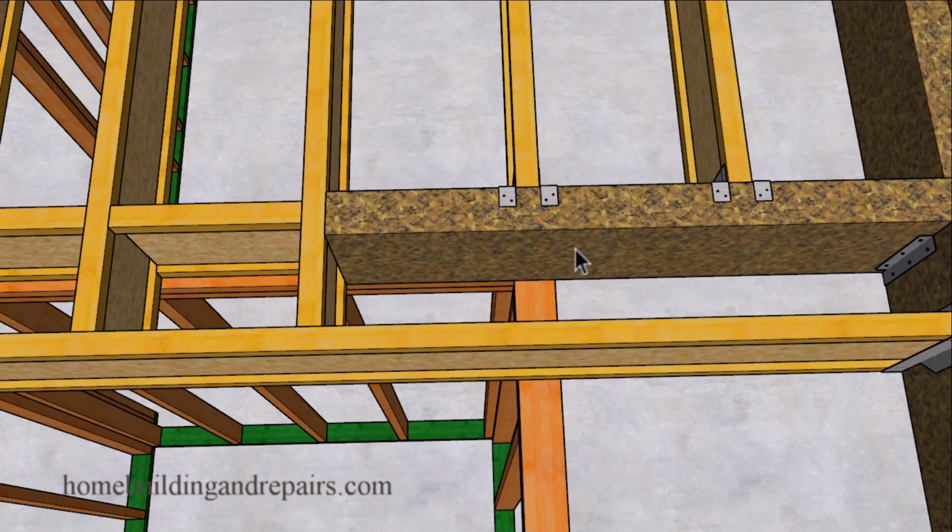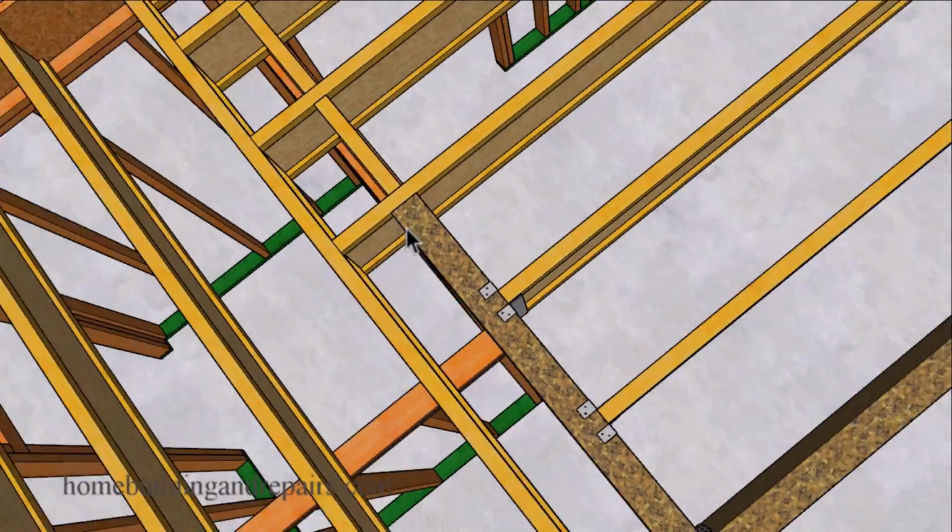And here's another thing you might want to do, and that would be to extend the beam if you have a little bit extra to spare on the beam. If not, you could always stop the beam over here. If, for example, you had like a 14-foot beam and this is where the 14-foot section ended. And I've been doing it for years. There's no need to order longer lumber to make something like this work. Just simply run it past a little bit so that you can get a little more bearing on the walls.